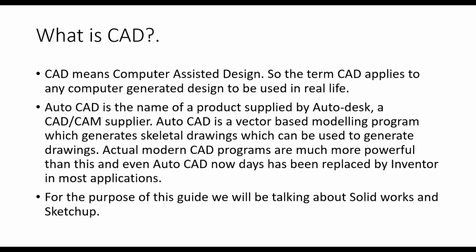For the purpose of this guide, we'll be talking about SolidWorks and SketchUp. Now, in the industry that you're working in, if you're working in cabinet making, it's most likely that they'll be using a program like Cabinet Vision or something like this that can export a CAD model directly into a CAM program, or can CAM a three-dimensional model using all the parts, and just DXF them straight away.